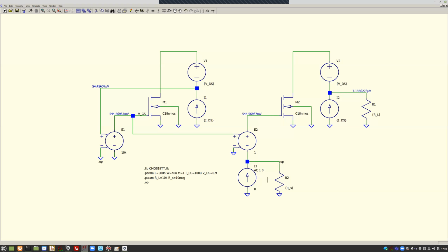But now I can do an AC analysis. AC is a little bit of a confusing word in simulation because it's also valid for DC, but they don't simulate DC. AC means small signal in SPICE. It takes the derivatives of all the nonlinear relations in the operating point and then calculates the transfer. So AC is used for small signal analysis, but small signal analysis would be the better word. AC is basically a confusing word, but everyone is used to it now. So that's why people are doing it.